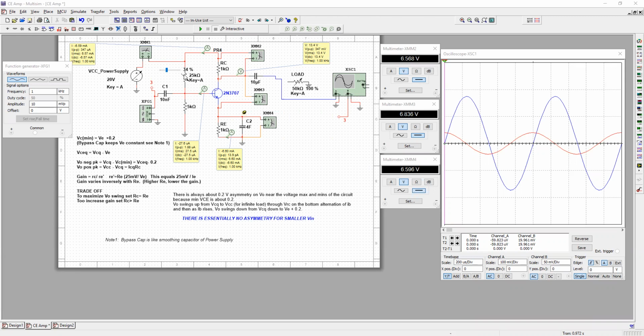We have a voltage divider here where we have a potentiometer set to about 34% of its full value. So 34% of 25 kilo ohms is what we have up here. And that is going to share voltage with the 5 kilo ohm below. So we'll only look at the DC components right now. We're going to ignore the capacitors, and we're going to ignore the input stage here, as well as a load that I have waiting in the wings.